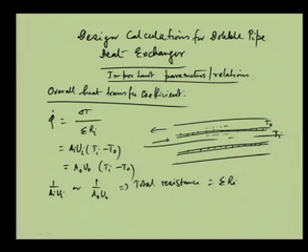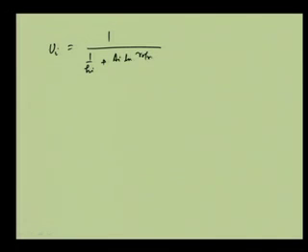These are based on the inside area of the inner pipe or the outside area of the inner pipe. So, based on that, Ui, as we have already discussed, will be equal to 1 by Hi plus Ai ln Ro by Ri divided by 2 pi K L, where K is the thermal conductivity of the wall material, plus Ai by Ao into 1 by Ho.